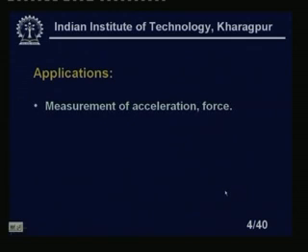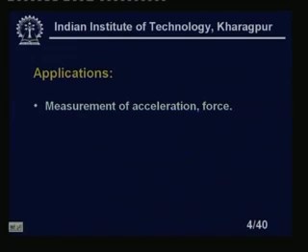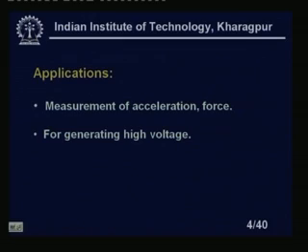Applications: measurement of acceleration and force. It is also extensively used in vibration analysis, crack detection, and thickness measurements. It is used for generating high voltage, because momentarily it will make a very high voltage, even though the current capability is very small, if I apply sudden high pressure or impact on the piezoelectric crystals.